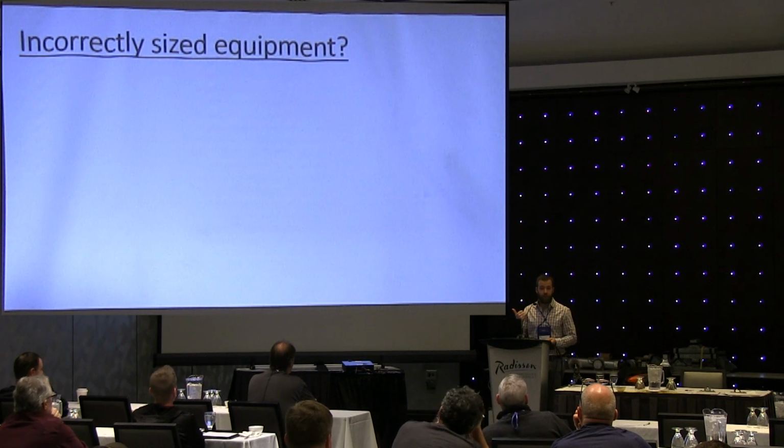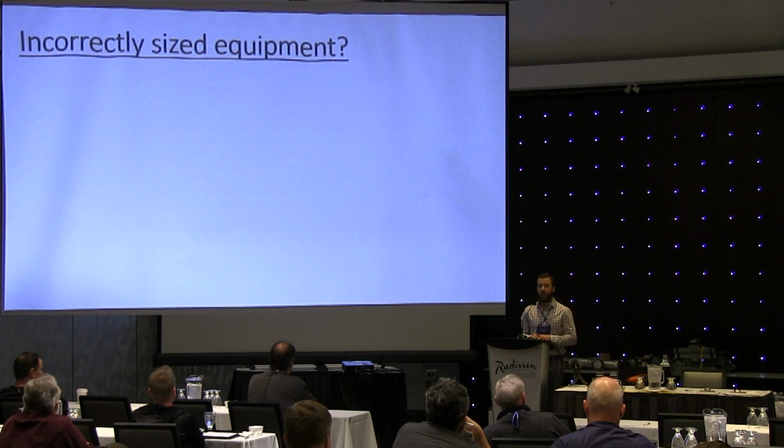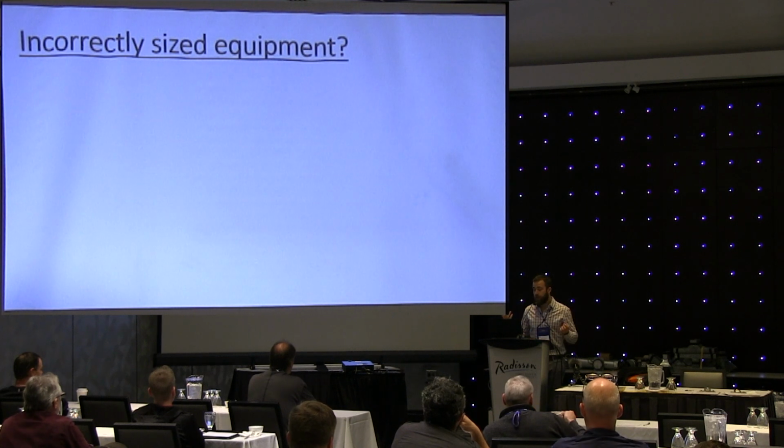Number one, the calculation methods themselves have some built-in safety factor, which, the less accurate they are, the more safety factor they want to build into it. And maybe people doing the calculations are building their own safety factors in. So you get all these things accumulating, and you get way higher loads than are actual in the house.